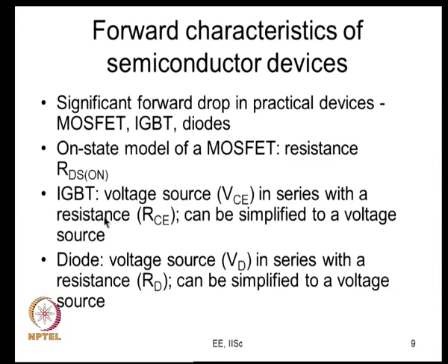If it is an IGBT, the forward characteristics can be modeled by, you can consider the IGBT to be a voltage source VCE in series with the resistance RCE.